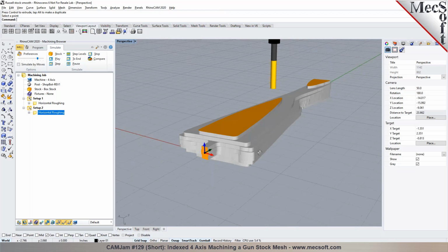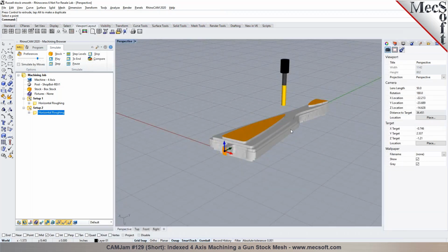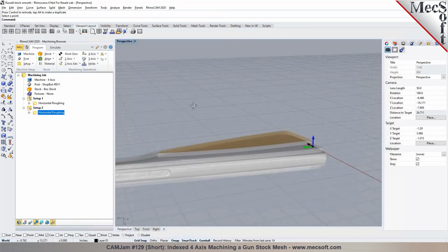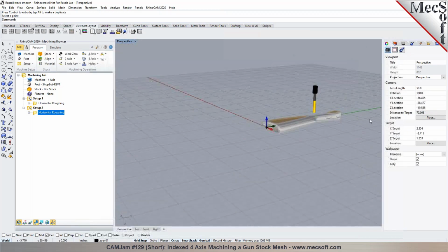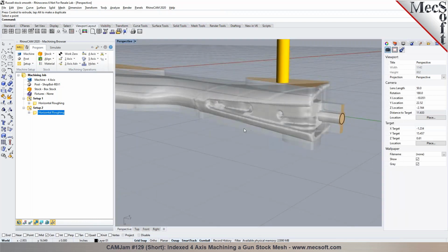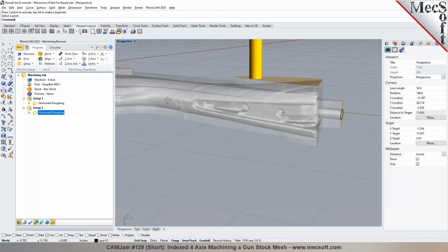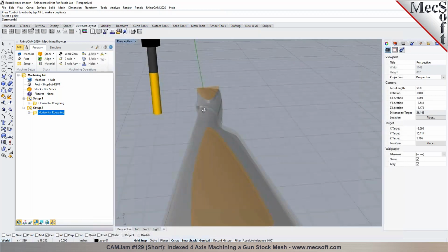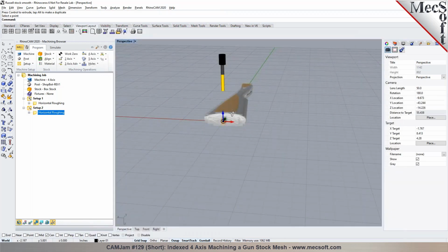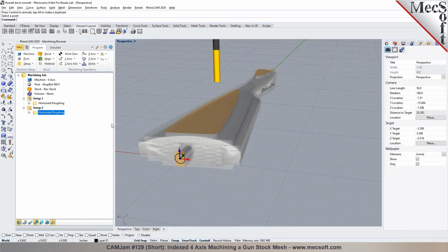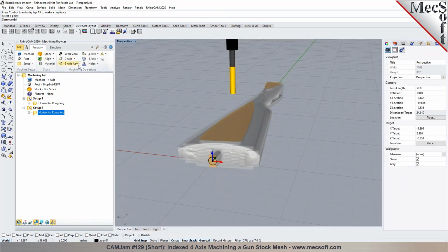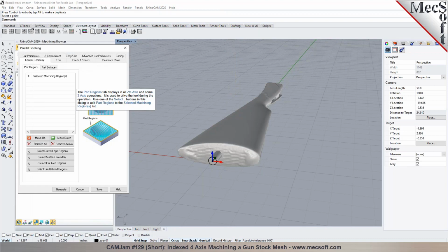Any questions, sir? Nope. Okay, so now that you've done your roughing from the two sides, if you want to go back and rough it from this additional side, we can rotate it to get to some of these detailed features in here, or you can go directly to a finishing process on those sides as well, because we have cleaned it up and brought it close to the net shape of the part, right? Right. So the next step is to do a finishing. We could do a finishing from this side we are already on. We could just go from a roughing process to a finishing process.